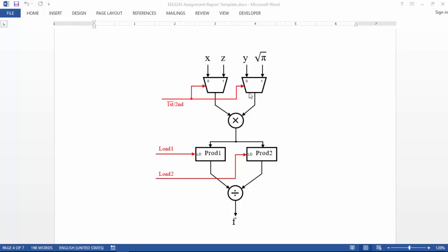To do that, we will code it first and then continue straight away with the test bench to test this first part. This first part is actually the first junction that the data flows in, and to test that we need to also code in our control unit the first state where the start signal is 1.